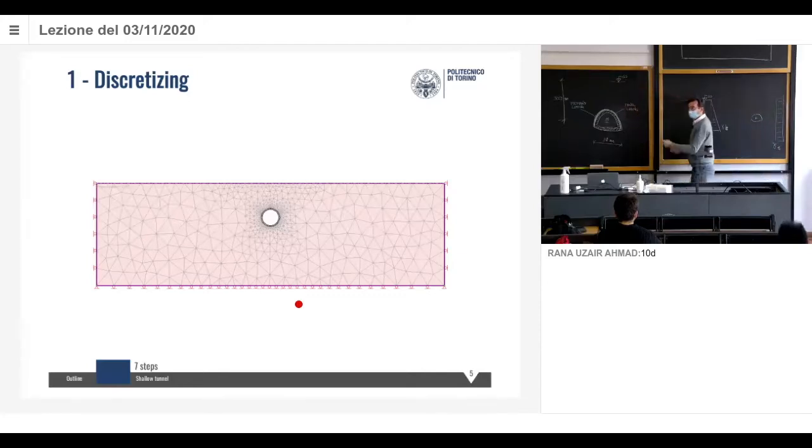Whereas, all what I said is wrong if we are in a situation like this. Because in that case, we have to do as she said, we have to stop the boundary here, and then we have an issue of boundary conditions. So we have to say, well, what kind of boundary conditions do we put here? Well, in case of a ground surface, it's going to be a free surface. In case of a deep tunnel, we will need to set boundary conditions. Okay? So the model is a schematic representation of reality. Always keep this in mind. So we may do strange things like going beyond the ground surface if we do it properly. Okay? So let's go back up here.